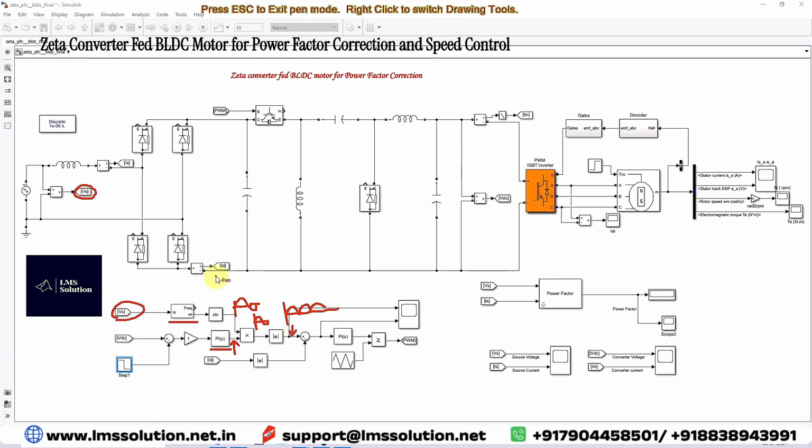Next, you have to measure the diode rectifier current here. Once again, you have to apply the absolute value, that means you convert the negative portion to positive. Here also you will get a positive response. We always get only the positive portion of that diode rectifier current. Next, you have to compare this reference current with this diode rectifier current.